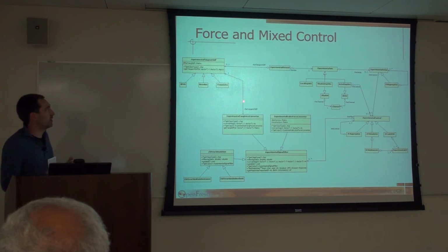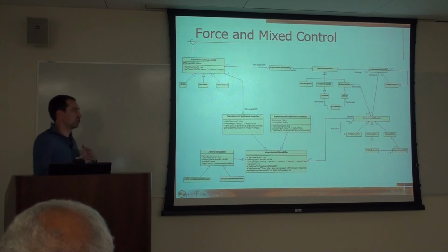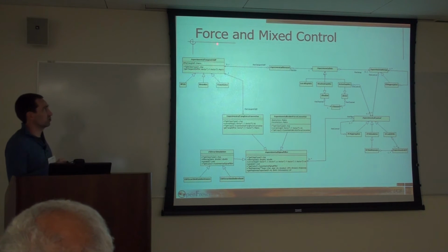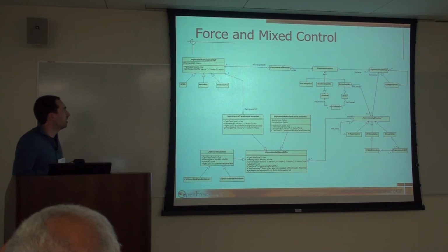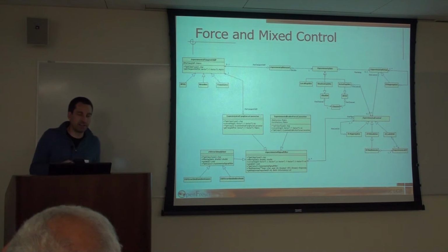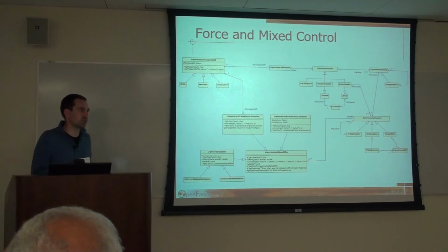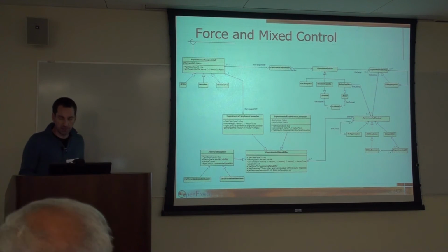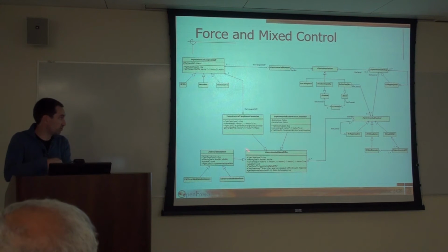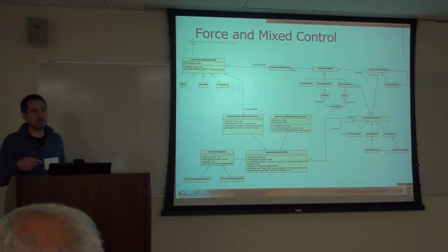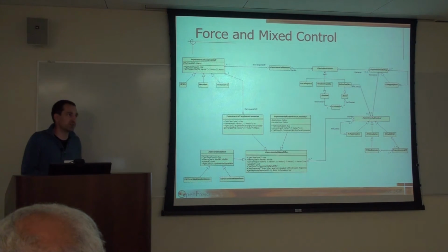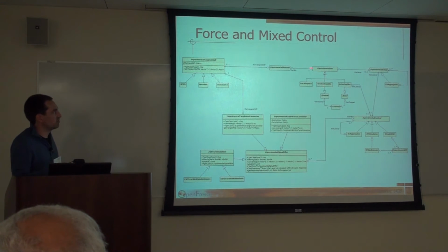Another special thing we have in OpenFresco, and are slowly bringing in, is force control and mixed force control capabilities. Hong Kim, a former student here, developed this, and it has been around for a while, but we haven't had time to roll it back into the OpenFresco code. It's been sitting on a branch development, but I'm now bringing it back in, so these capabilities are starting to become available. It's very hard to do a tangent stiffness matrix in a hybrid simulation, and now we have some capabilities for that.